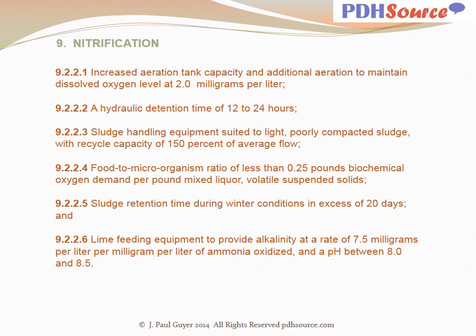A hydraulic detention time of 12 to 24 hours. Sludge handling equipment suited to light, poorly compacted sludge with recycle capacity of 100% of average flow. Food to microorganism ratio of less than 0.25 pounds biochemical oxygen demand per pound mixed liquor volatile suspended solids.